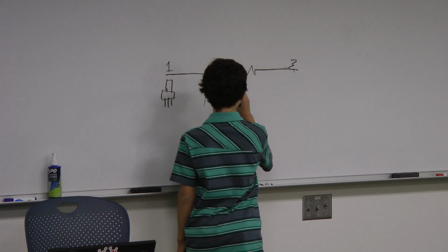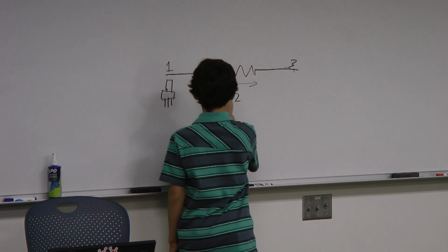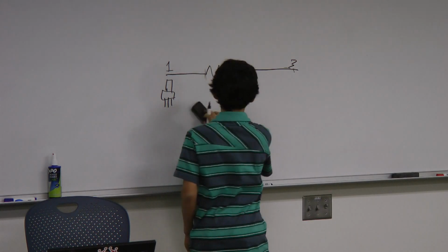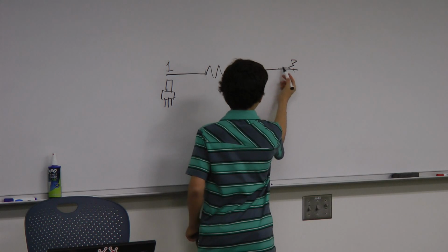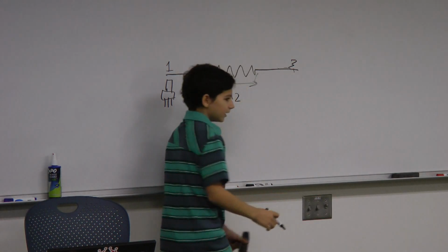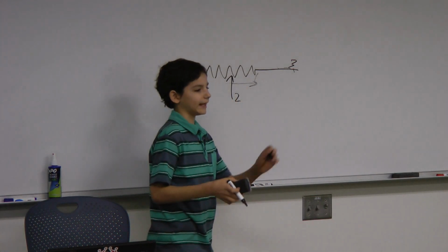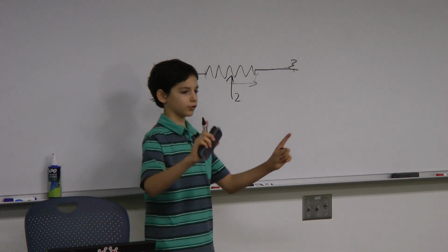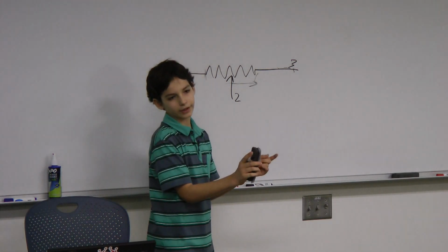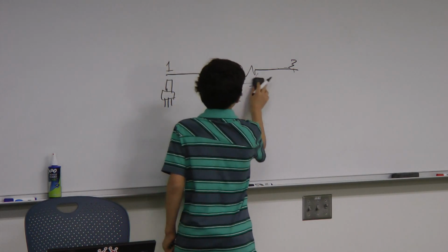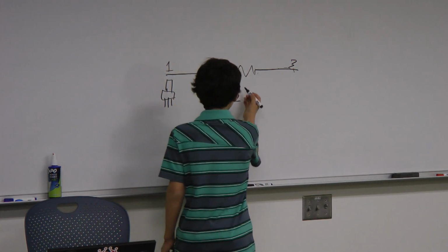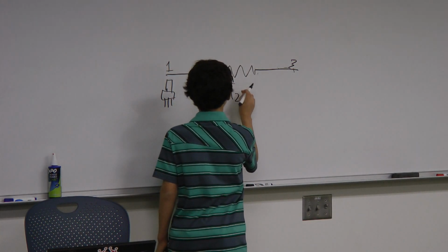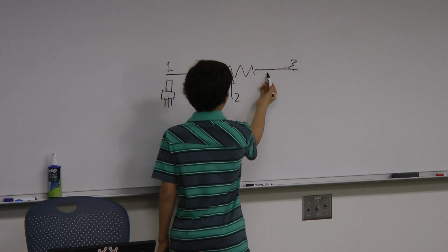When you turn it all the way the other way, it then connects the other pin to it. If you're building something where you want a label for, like, this way is one thing and this way is the other, you might have to swap the 2 outer pins, or if it's inverted maybe. And then if we put it in the middle, it's about half the voltage.